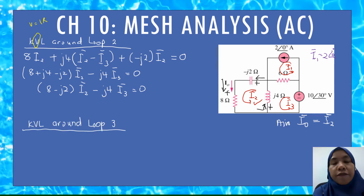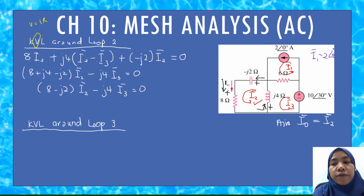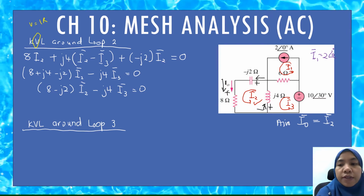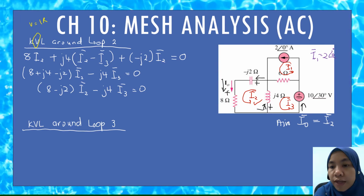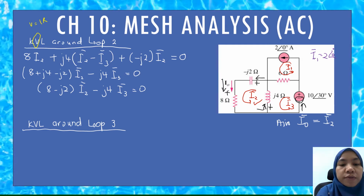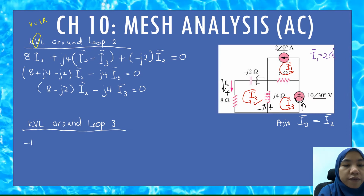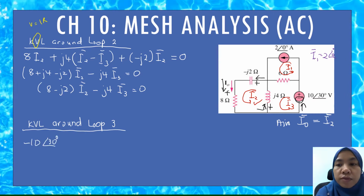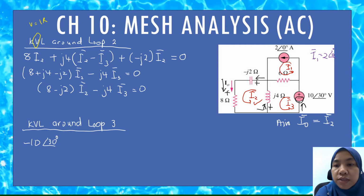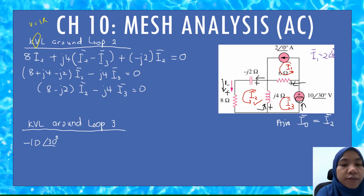Next, KVL around loop 3. If you start from the voltage source 10 with 30 degree, the current is entering the negative side. So you start with that. This is negative 10 with 30 degree, and then we go to 6 ohms here. Current is entering a passive element, so it should have a plus.